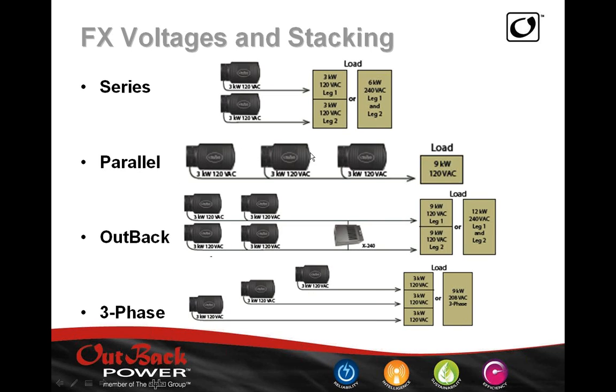The parallel stacking is a little different. Here we have all 3 inverters feeding the same phase. We're paralleling all three inverters, and you could actually have up to 10 parallel inverters all feeding the same phase.